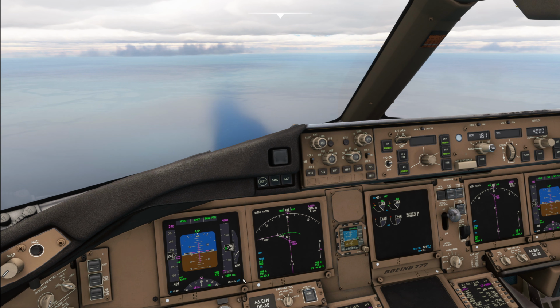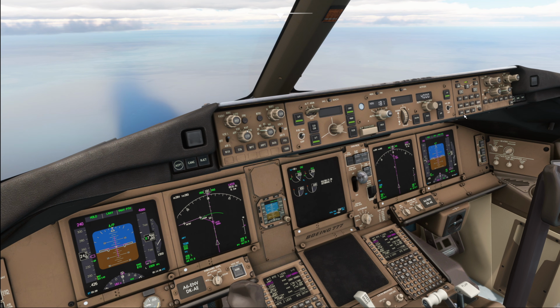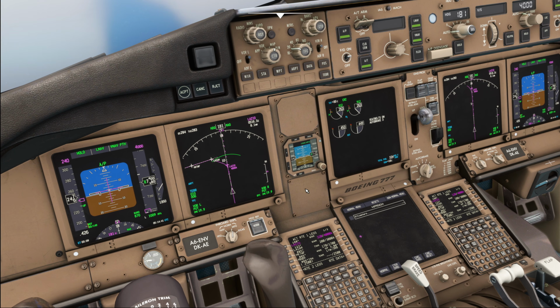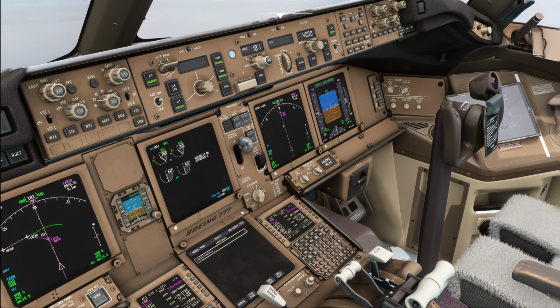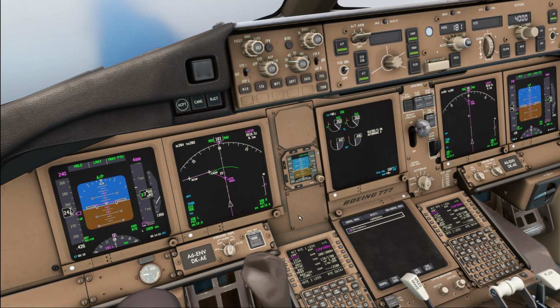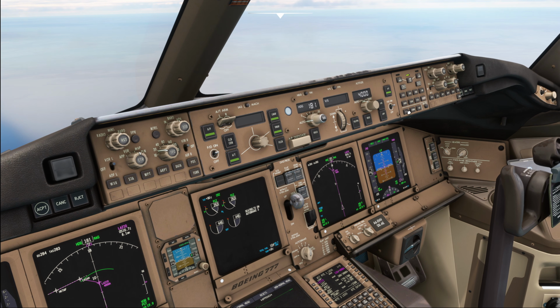So, I've just pressed the B key, you might have seen that, and changed my QNH to the current QNH. So when that is done, and when we read the approach checklist, take that altimeter challenge over here seriously. Don't just check that any QNH is set, but use all available means to check that the correct QNH is set. You can always compare it against the latest that was reported on the ATIS. You can always ask ATC to confirm the altimeter setting for you. When that is done, we can complete the approach checklist.